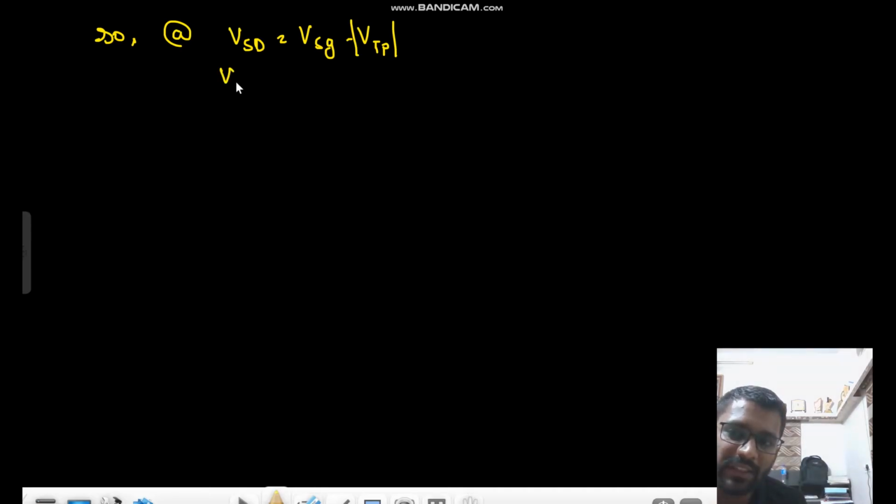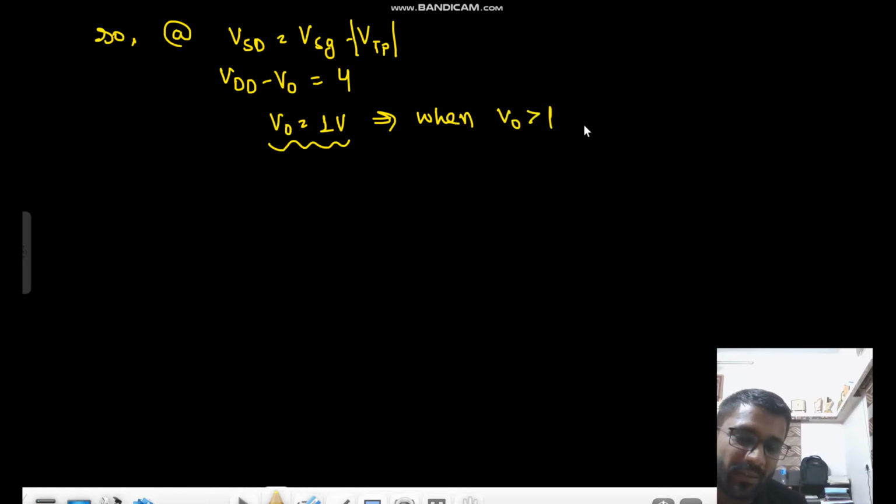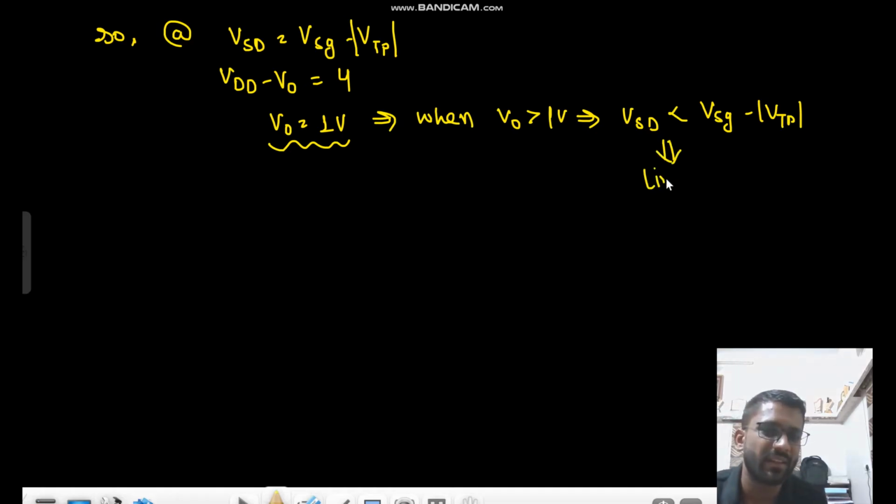So at the point where VSD equals VSG minus mod of VTP. Okay. So what is your VSD? VSD is VDD minus V naught. Your VSG minus VT is 4 volt. So VDD is 5 volt, so V naught would be equal to 1 volt. Okay. So when V naught is greater than 1 volt, at that time your VSD is less than VSG minus VTP. That means at that time we are moving towards the linear region.